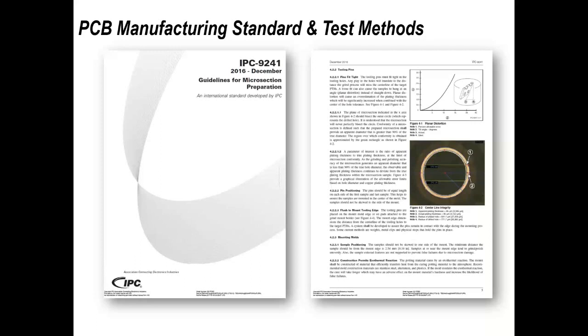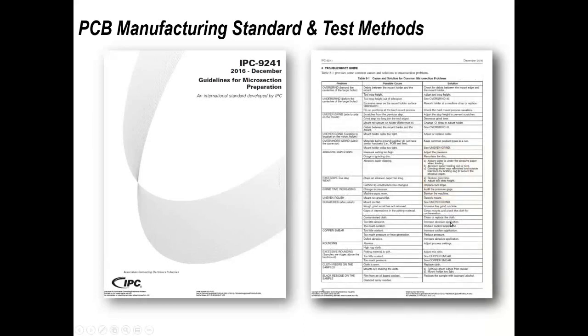And of course, if you don't prepare the samples accurately, then you get misleading information, and that could be embarrassing if you complain to a supplier that you haven't got what you pay for, when it's actually due to how you've examined the part. So again, the reference there is very useful. In addition, it shows you some of the reasons why certain defects within microsections happen. If you're preparing a sample and perhaps you haven't done it the right way, it shows what things you might expect to see and the possible causes of those imperfections.